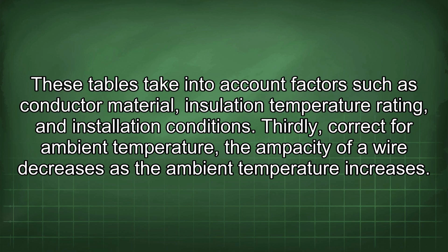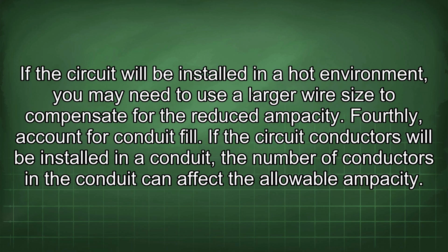Thirdly, correct for ambient temperature. The ampacity of a wire decreases as the ambient temperature increases. If the circuit will be installed in a hot environment, you may need to use a larger wire size to compensate for the reduced ampacity.